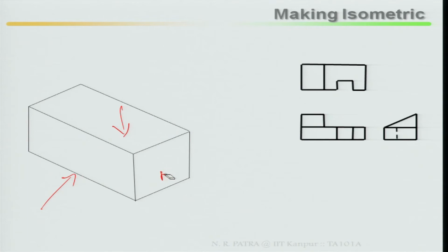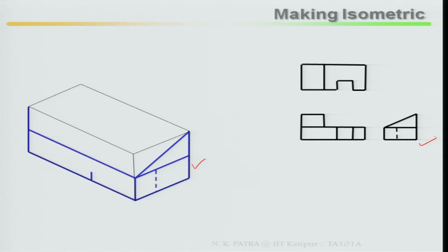If I take it this way, you can look at these animations, how interesting it is. Take it one by one. First I draw the side view as it is, not doing anything else. This is the side view. Whatever you are seeing here is your side view. Then draw your front view as it is. Now it is your front view. Similarly, draw your top view. This is what you have done.